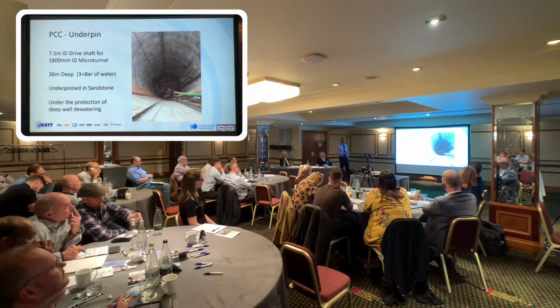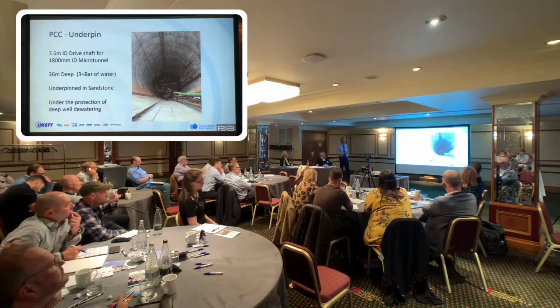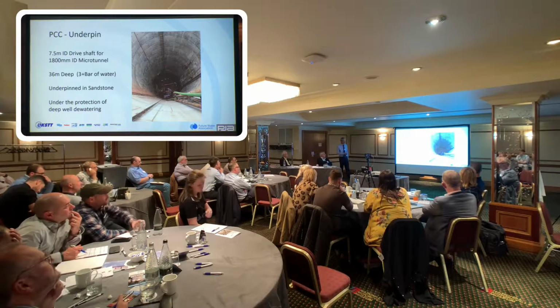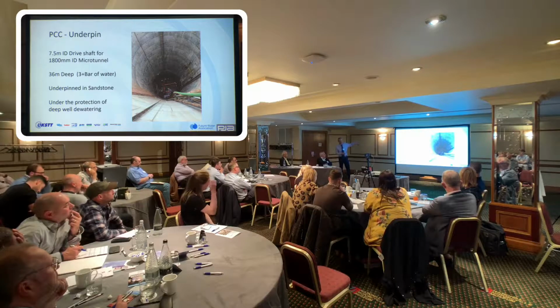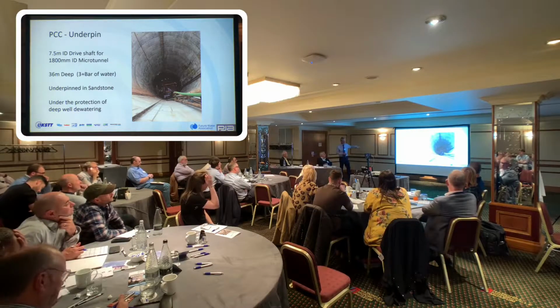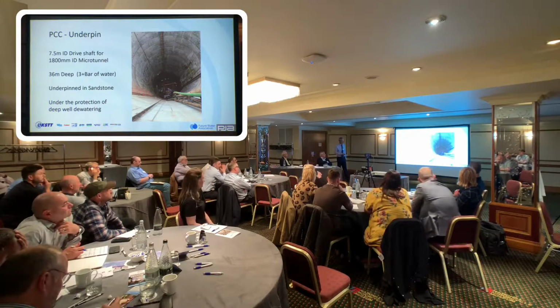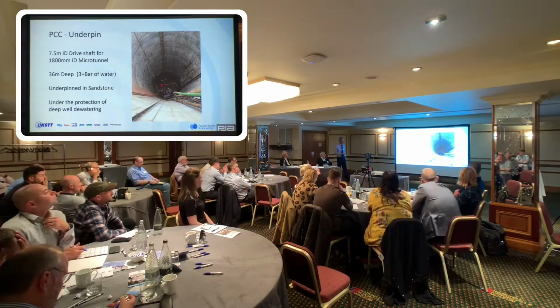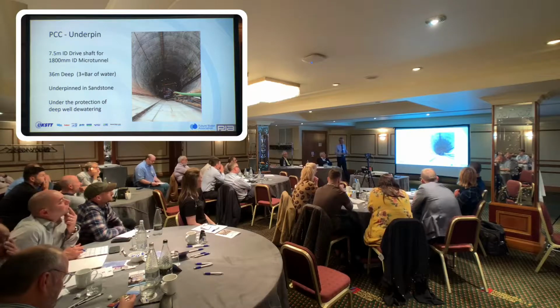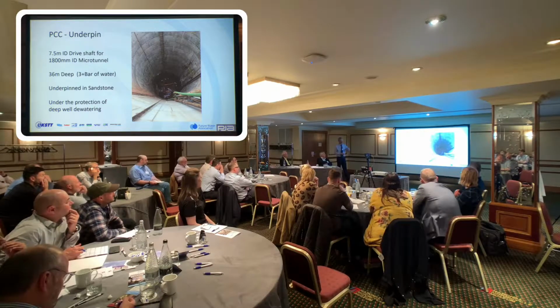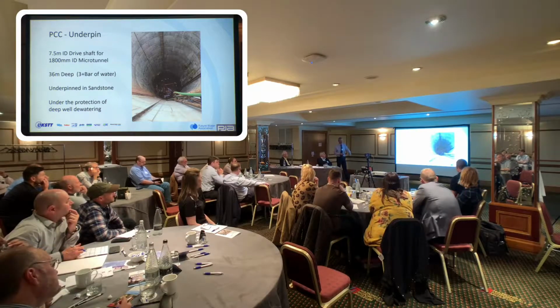And this is another picture of an underpinned shaft. This is actually one of the shafts I showed you a photograph of the site earlier on, the BRP project. So this is 36 metres deep. 36 metres is beyond the reach of hydraulic grabs, extending grabs.